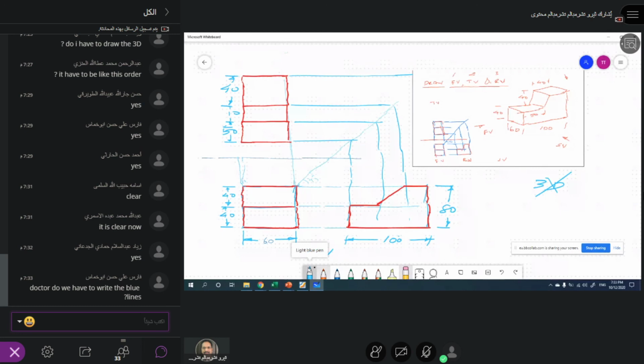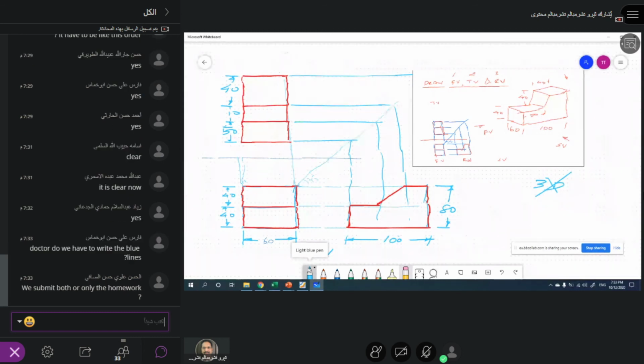Very, very important. All of these projection lines or construction lines are very important. You know why? You don't need to measure again. See, you just project it. You already see, you just project it. The 60 is already there on the top. And if you project the side view, 80 is already there. So you don't worry about this. Otherwise, every time you have to measure it. You understand? So draw the construction lines. Very important. So for construction lines you should use 2H, and this should be HB.